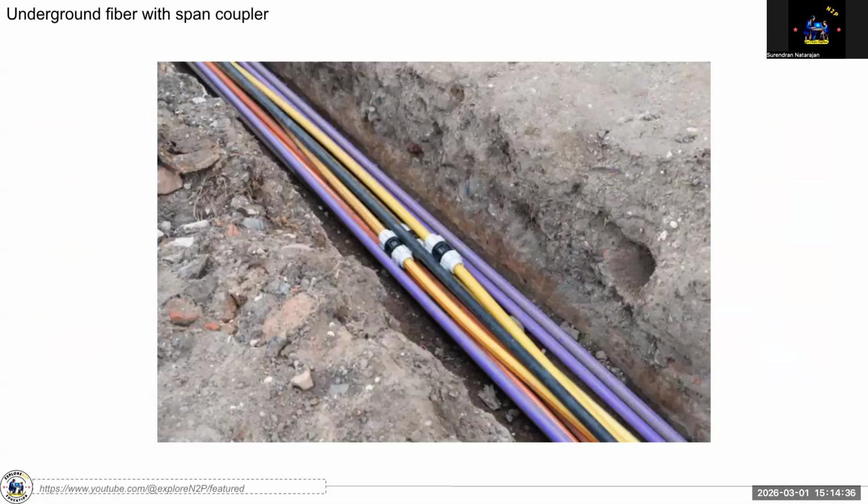Usually, here, the first thing they will do is lay only the PVC pipes. They will not lay the fiber, so they will put only the plastic duct. Once they run the ducting, they couple it over the same distance, using PVC duct couplers. Once it is done, people sit at one end and, using a blowing machine, they send the fiber inside it.